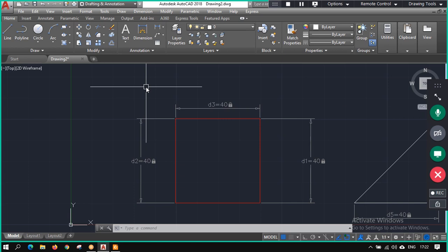It's not for decoration or any other purpose, that is the secondary reason. The primary reason for using fillet or chamfer is to decrease the amount of stress concentration. The stress concentration does not get eliminated entirely, but it can be decreased. Fine.